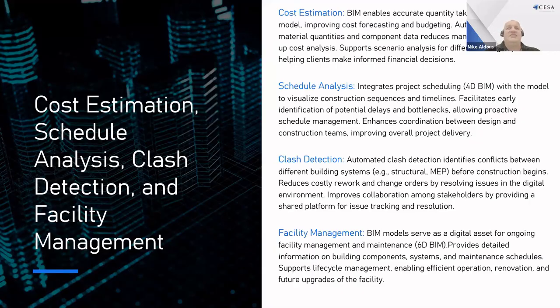And it highlights the fact that you can't build the second floor before the pile caps are done. And it looks at that from a very visual perspective. You may not pick it up immediately in reams and reams of documentation, but when you see the second floor suspended by sky hooks with no supporting infrastructure below it, it's very clear that there's something wrong with the schedule. So this has been a very powerful tool from a BIM perspective.